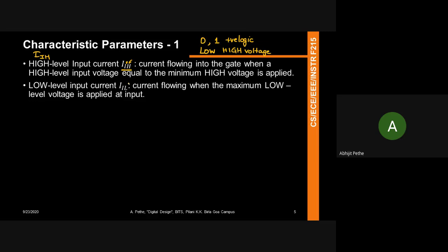We are talking about digital systems which are two-state digital systems, or two-state Boolean algebra, right? We are looking at the simplest form of Boolean algebra, which is a two-state Boolean algebra. So in that, we talk about two states, high and low. At both these states, different currents are flowing into the gate. So again, remember, just because voltage is high and low doesn't mean current is equal. Current is also different between the high and low voltage, right?